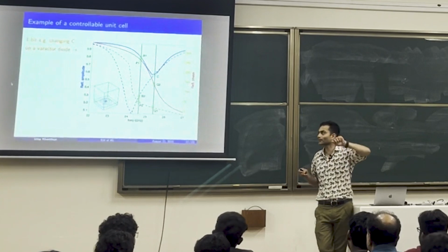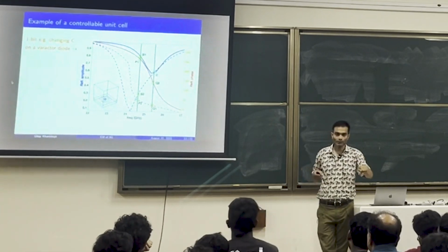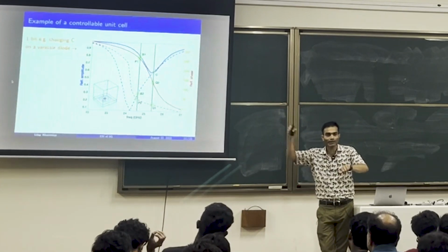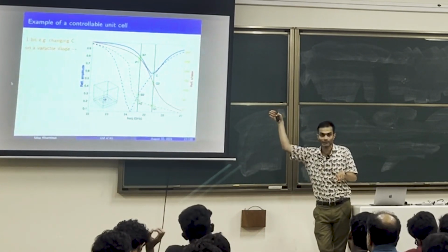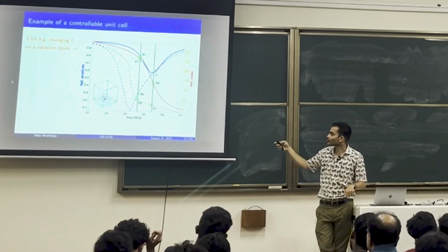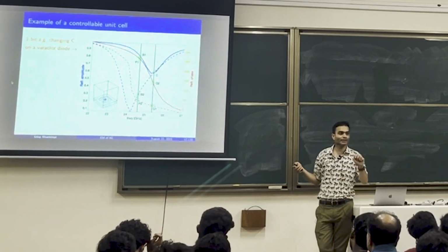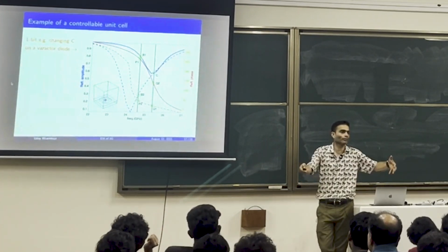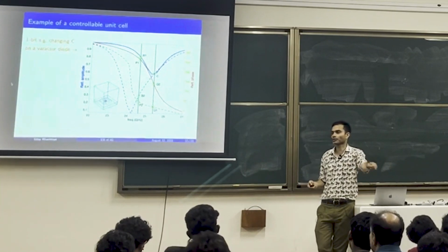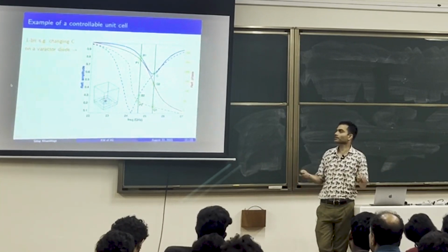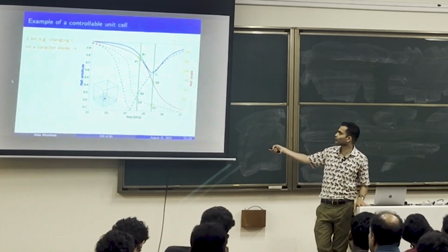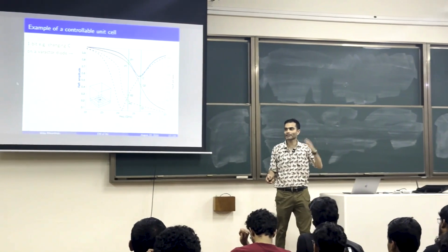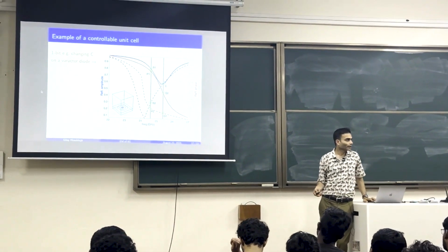So that means that when the diode is in state 1, the reflection phase is 0 degrees. When the diode is in another state, the reflection phase is different by 180 degrees. Right? So I can achieve a control because I can change the biasing voltage of the diode electronically. I don't have to do anything. I can have a full biasing network, let's say 2 volts or 4 volts. When it is 2 volts, the phase is P1. When it is 4 volts, the phase is P2. Right? So this is how I achieve the dynamic control.